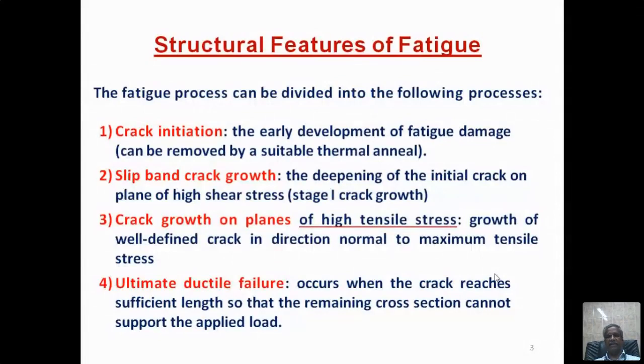That is the second stage, deepening of the initial crack on the plane of high shear stress. You know that if you apply a pulling force, a tensile force, the maximum shear stress, the critically resolved shear stress, will act along the plane at 45 degrees to the applied tensile stress. That plane will have the high shear stress, so the crack will grow along the maximum shear stress plane.